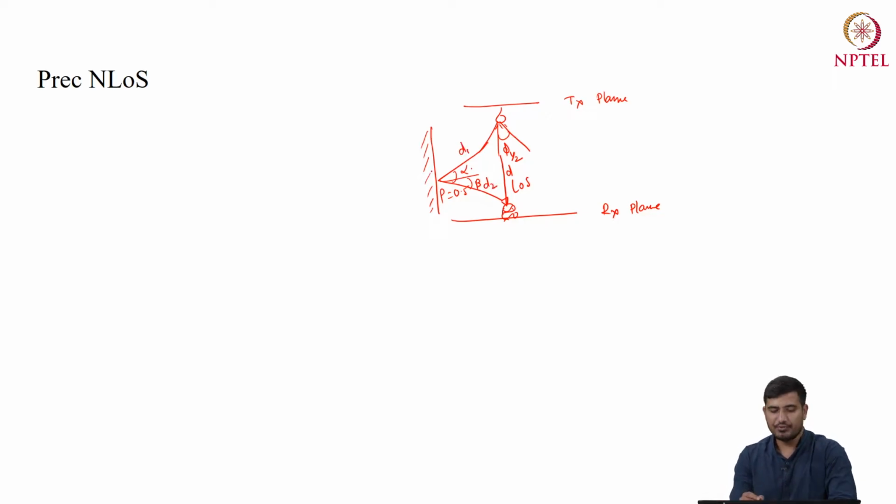In order to model this non-line of sight channel gain, you need to model this reflection. This reflection can be a one point reflection, in which the LED light is reflected at one point from the wall and received at the PD, or it can be a two point reflection, where light is reflected from two points on the area and then received at the receiver.